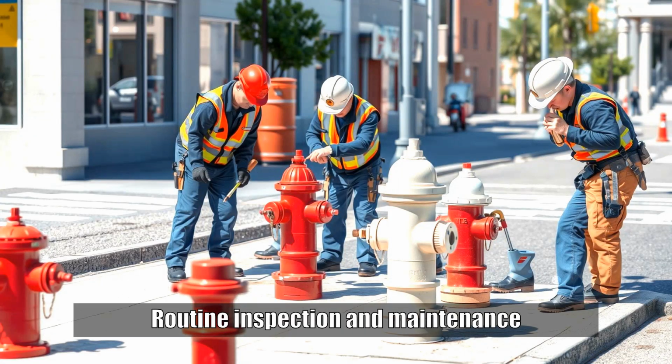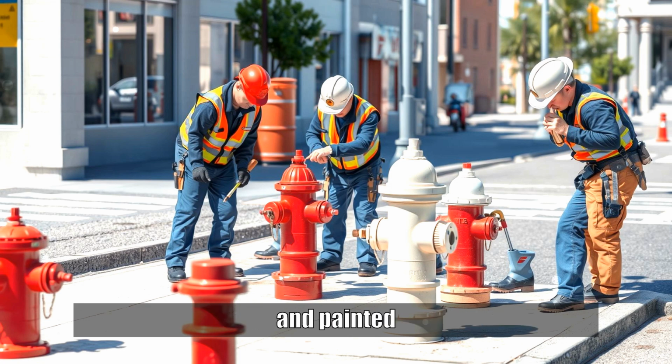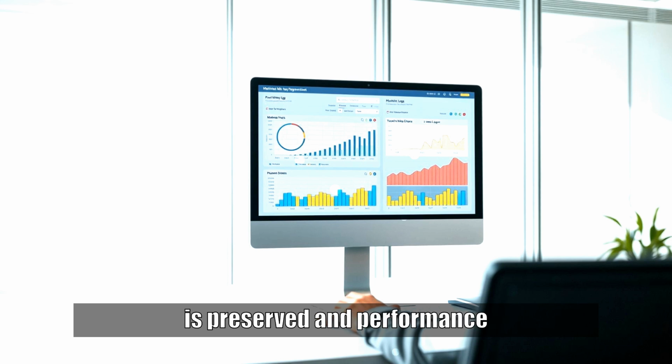Routine inspection and maintenance schedules must be established, usually biannually, where hydrants are operated, checked for leaks, lubricated, and painted. Valves are exercised to prevent seizing, and drainage is verified. Maintenance logs are often digitized, ensuring historical data is preserved and performance trends are monitored.